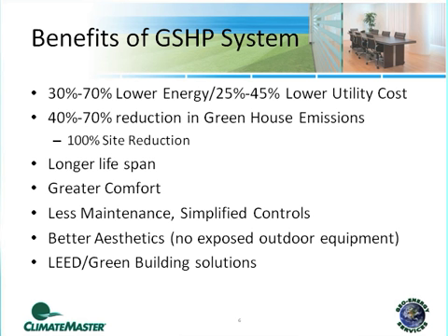But certainly on every LEED project, on that first cut level, we should always be evaluated. When you look at LEED projects, when LEED was initially going back in the early 2000s, and even now to some extent, when you look at some of the highest LEED-rated projects that are out there in the United States, if you look at those in a lot of detail, you'll know that the mechanical systems on the majority of those projects are ground source heat pump systems.